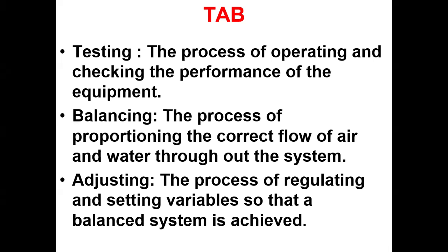Whatever. That's it. Then maybe they have other calculations. I'm simply saying it is a thumb rule concept. If you have some dedicated concepts, they will be there. The main concept is like this itself, guys. We know that for each diffuser, as per the calculations, there is a certain velocity. That's how we did it, isn't it? 650 FPM on this specific diffuser. So we must check whether it's coming or not.